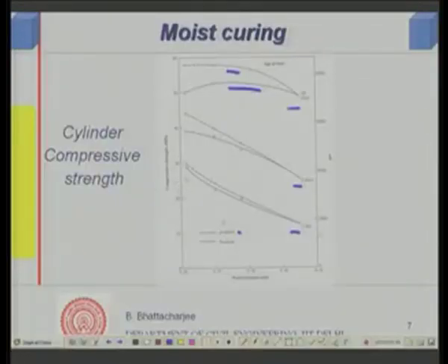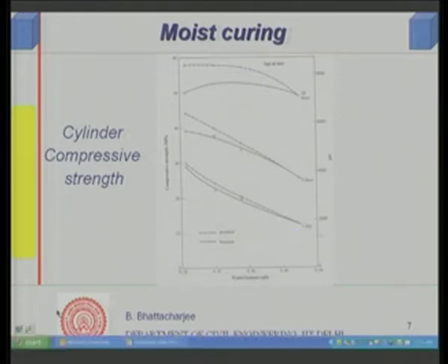So, we can see that ponded is better, especially when you have low water cement ratio, but in any case ponded means 100% replacement of water. Hessian is quite good. So, this idea one can use. Commonly Hessian is used on vertical surfaces and also on horizontal surfaces, but it is okay, whatever is possible one can do, both would give you equally good results. Right. Now, let us see other methods.